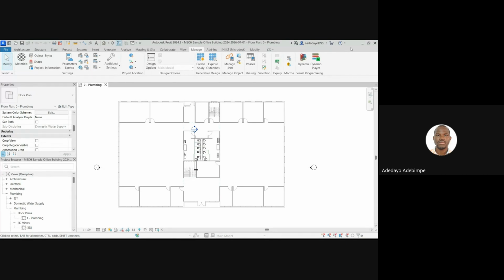What a type catalog is supposed to do is give you options, which limits the number of families. Let's say I have a sanitary fixture type catalog, maybe a toilet seat. I can have 100 different types under a type catalog. When I load the family, it will give me an option to select the specific types I want. However, if I drag it in, it might bring in everything, and that can be a very large folder. So both work, but the best practice is to insert.